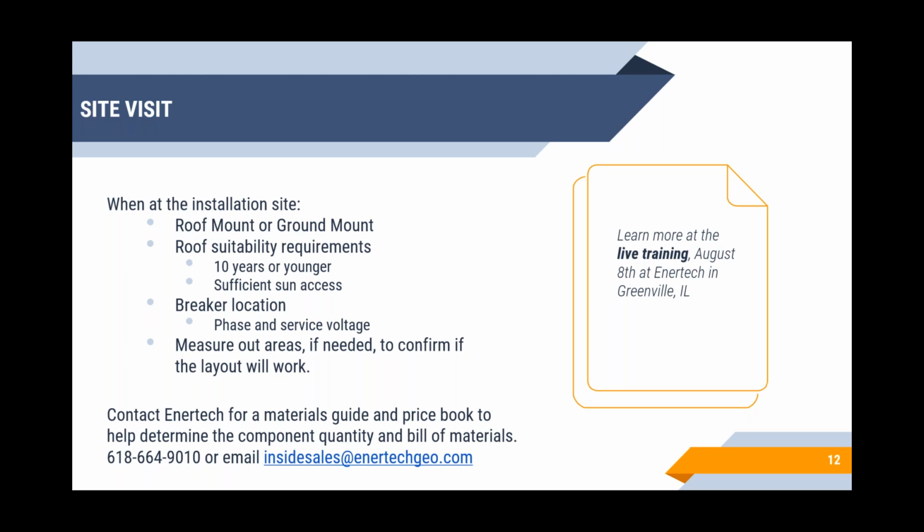You also want to see if that roof has sufficient sun access to be suitable for solar as well. If you're there, you also want to try to find out where your breaker location is, and also figure out the phase and service voltage you're going to be working with, because those are going to dictate what type of inverter and equipment you're using on that system. If it is a roof mount and you have a proposed layout for that roof, but you think it may be a little tight, be sure to go ahead and get up on that roof and measure out the areas that you're going to need just to make sure that system will fit.